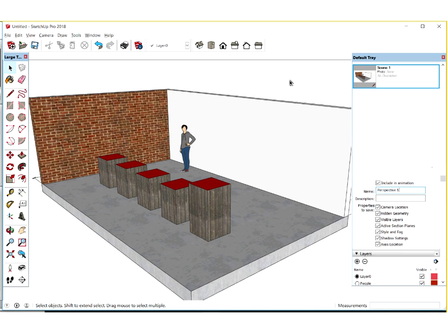If you're doing a big project and it's got a kitchen and a lounge room, name those perspectives per room and per view. Give them meaningful names. When you work in a team environment, someone else is going to want to be able to find your scenes. If you have scenes 1 to 50, it's going to be pretty hard for someone to sort out what's what. And just hit enter once you've typed in a scene name, otherwise it won't necessarily register. So that scene is saved there.